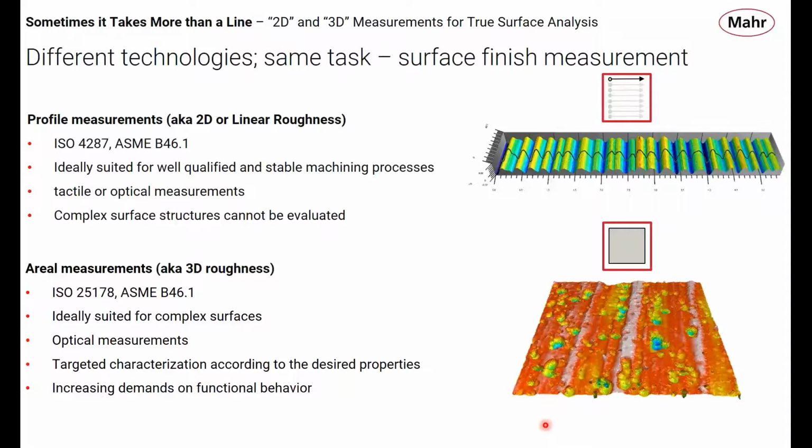We can look at our RA value and say, oh, RA is climbing, it must mean we have some tool wear, time to replace some tooling, or RA is climbing up, our feed rate must be off, or RA is dropping, the laser must be too hot on the welder, or RA is climbing again. So these very simple things, we can look at RA and we know exactly, from our 50 years of experience with this process, our 100 years of experience with this process, we know when RA does that, we need to go look at this. Well understood process. These profile measurements are great for that.